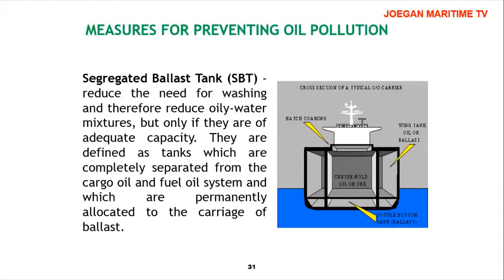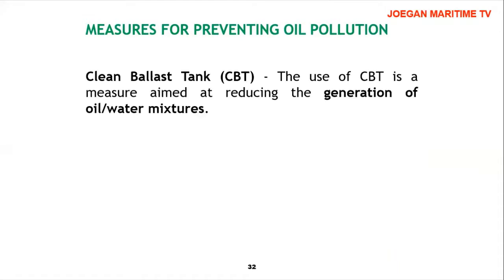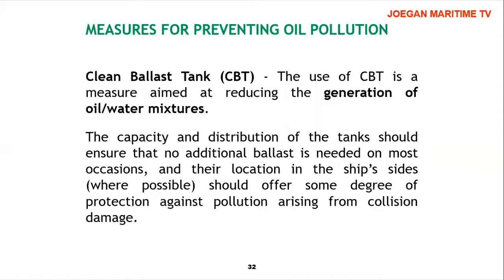Measures for preventing oil pollution: segregated ballast tanks reduce the need for washing and therefore reduce oily water mixtures, but only if there is adequate capacity. Clean ballast tanks. The use of clean ballast tanks is a measure aimed at reducing the generation of oil water mixtures.